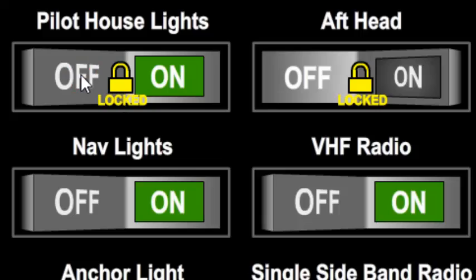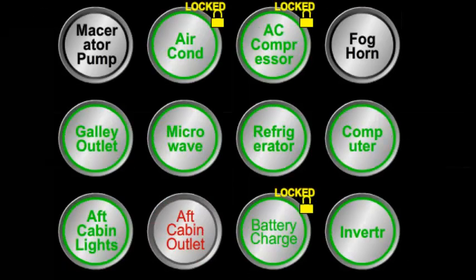There are some other components that display and control switch status. They are the push-button switches and have exactly the same functionality as the rocker switch. Here we can see the metallic push buttons. The color of the ring and the text are custom set for the on, off, and trip values during the creation of the favorite screen. These buttons have been set to show green when they are on and black when off, and flashing red when tripped. Touching the button will change it from the off state to the on state, and then another touch changes it back to the off state.